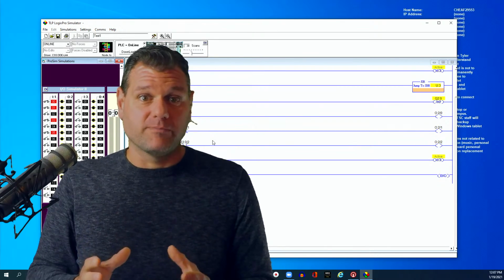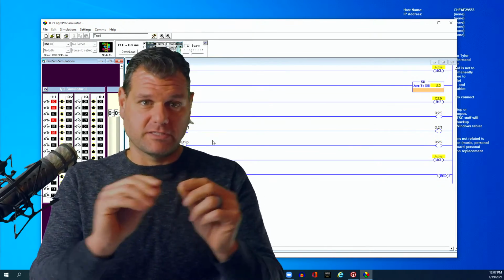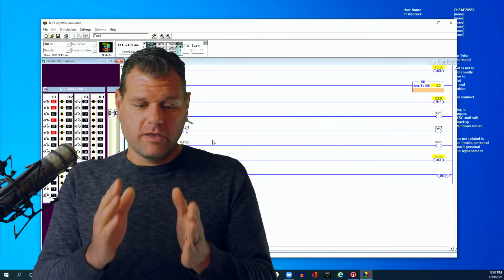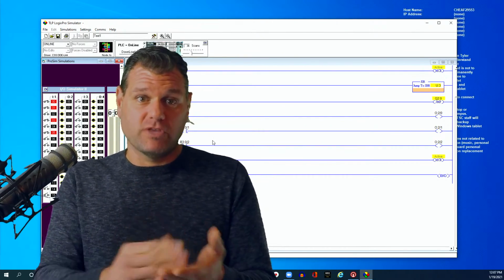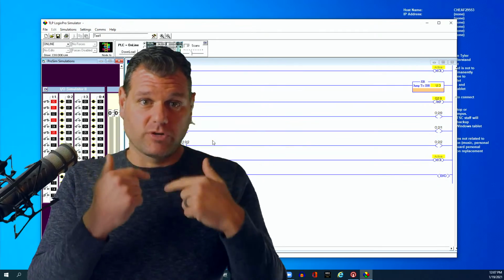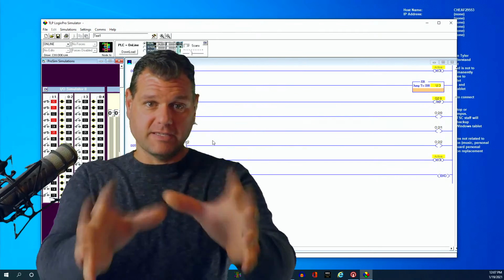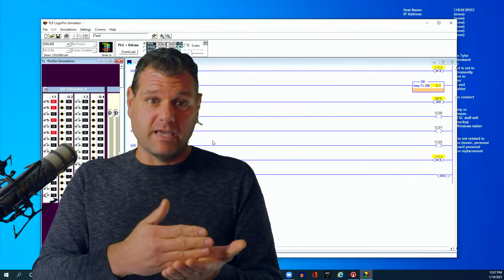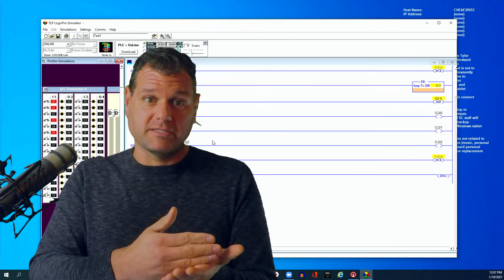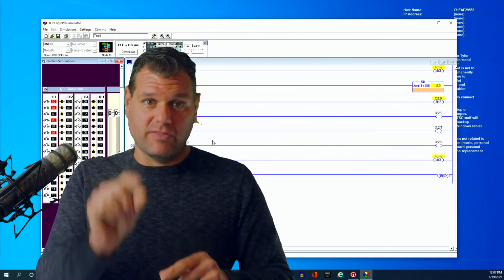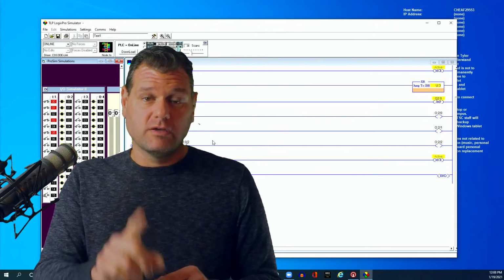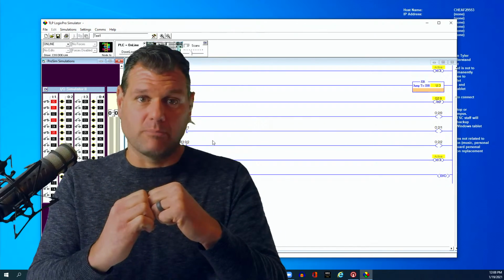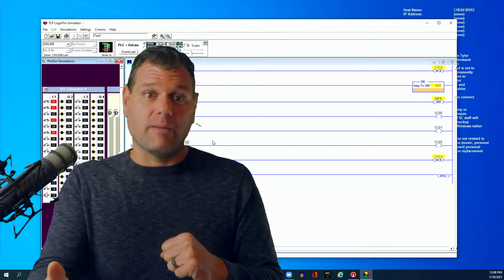Same thing happens here. There's a mask, which is basically a 16-digit word. It's 16 ones and zeros. If there's a one in place, it passes the information through, just like if we're not wearing any mask, right? It sees everything without being blocked. If there is a mask in place, then in that digit location, if it's a zero, it's basically going to block it and say this information cannot pass.